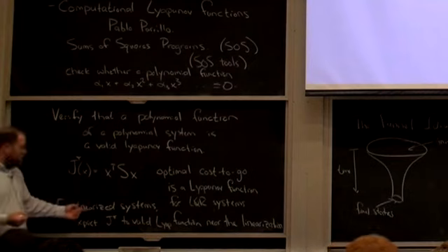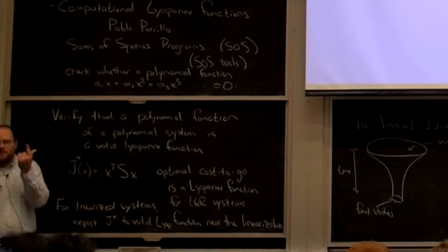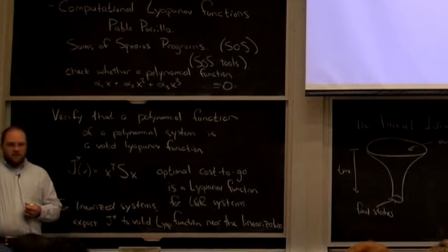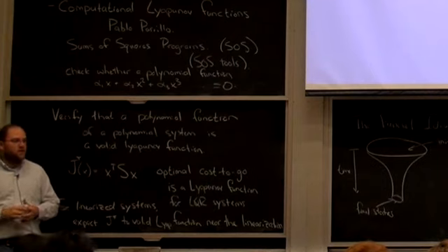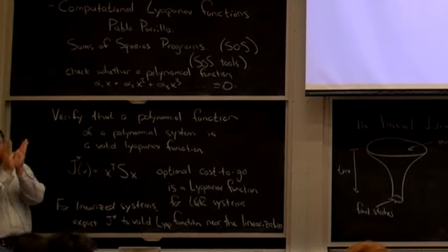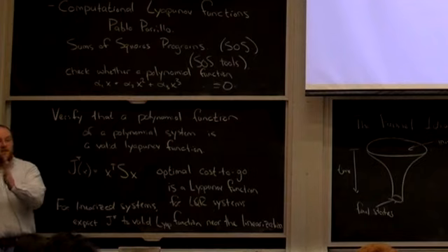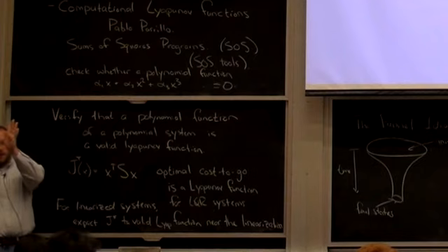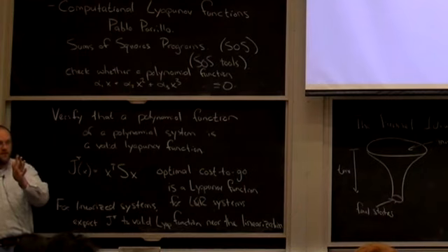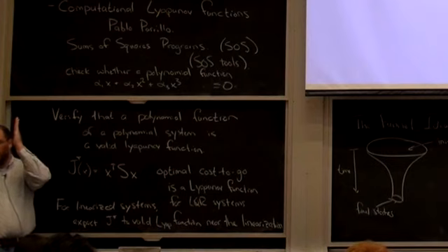You remember when we're taking a linearization and doing LQR, we already know that the basin of attraction is going to be something finite. We talked about that with the acrobot. I do a linearization around the top. I know if I'm near that point, it's got some small finite basin of attraction. If I'm inside that region, it'll go to the goal. If I'm outside that, then the linear controller design isn't valid for the nonlinear system. Eventually, you're going to get far enough away that it's not going to work. I think I even showed a simulation of it doing something crazy. So we designed a controller that got up there, and then we turned on the linear controller. All was good.